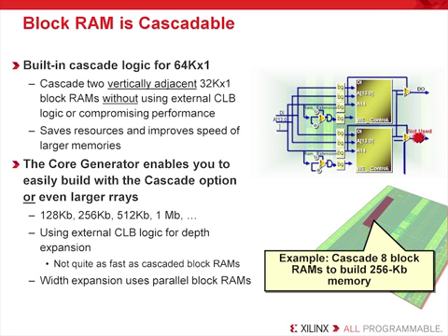Virtex 6 block memories allow for two RAMs to be connected together with the dedicated routing resources or cascade resources. This is important because it enables you to preserve the timing associated with a block RAM, but is only allowed between two neighboring RAMs. You cannot cascade more than two RAMs. Also note that Spartan 6 does not have this feature.